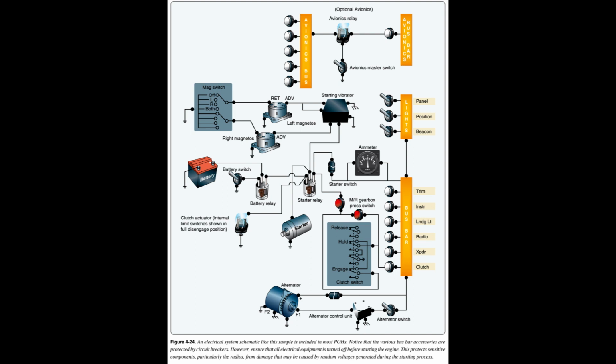Current from the alternator or generator is delivered through a voltage regulator to a bus bar. The voltage regulator maintains the constant voltage required by the electrical system by regulating the output of the alternator or generator. An over-voltage control may be incorporated to prevent excessive voltage, which may damage the electrical components. The bus bar serves to distribute the current to the various electrical components of the helicopter.